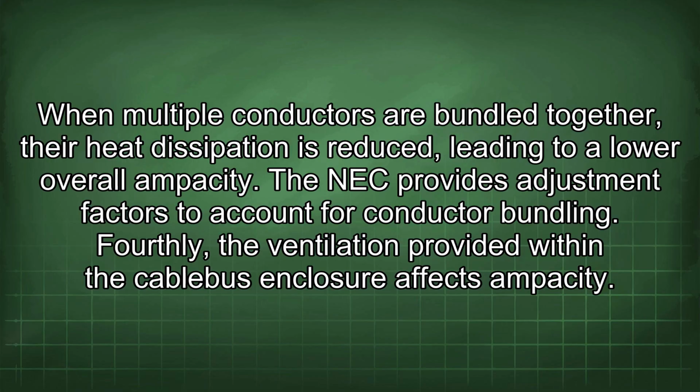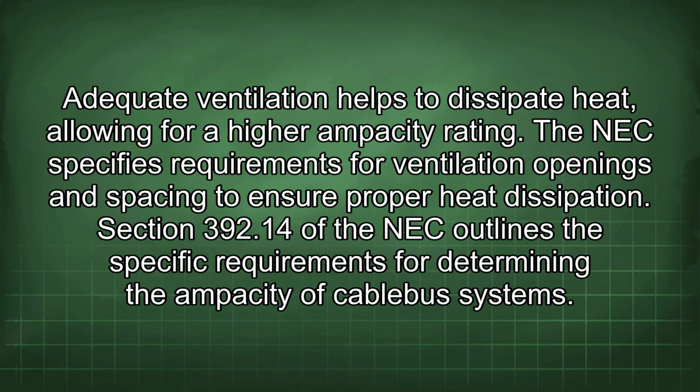Fourthly, the ventilation provided within the cablebus enclosure affects ampacity. Adequate ventilation helps to dissipate heat, allowing for a higher ampacity rating. The NEC specifies requirements for ventilation openings and spacing to ensure proper heat dissipation.